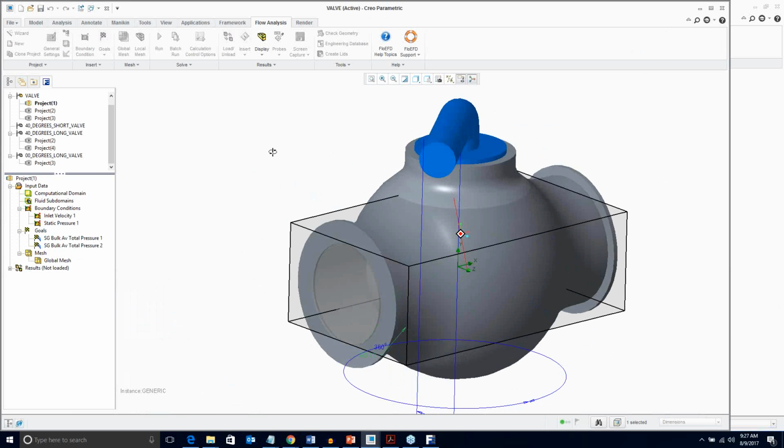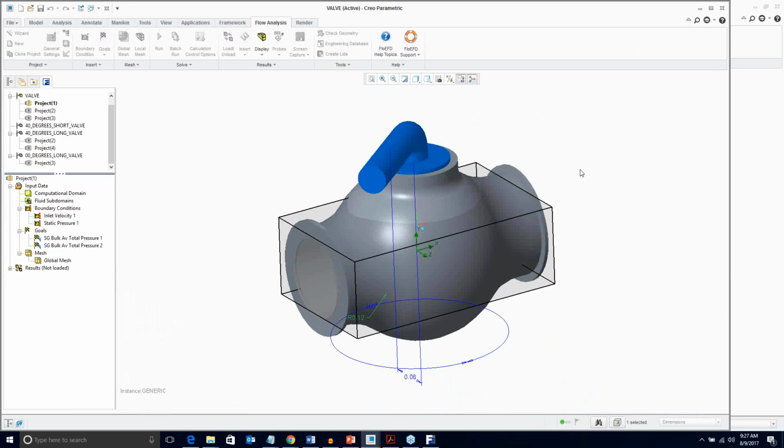In fact, one of the transient analyses we did for a customer recently was a case where they're making a thermos flask, so there's minimal heat loss through conduction and minimal through convection, but it does exist. Primarily it's through radiation. And it's a time varying thing, right? So heat loss varies as you go in time. FloEFD was able to predict how long your thermos flask can sit in, for example, an 80 degrees Fahrenheit room before it cools down to a certain temperature, right? So the cool down time.